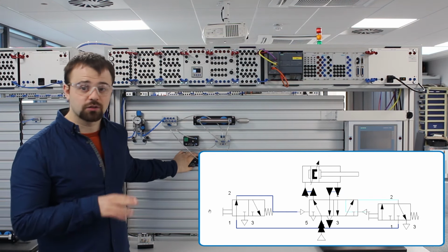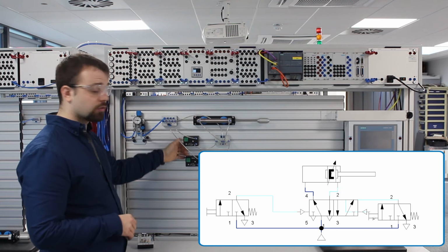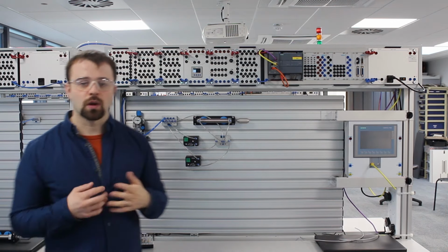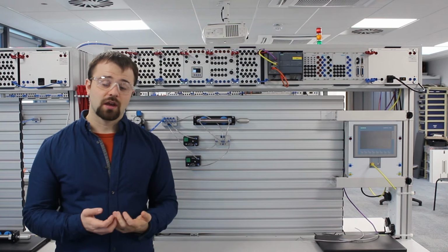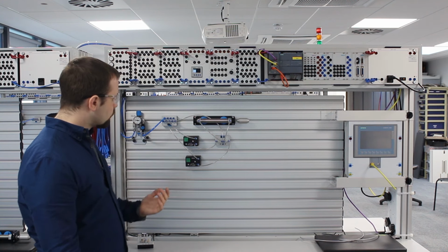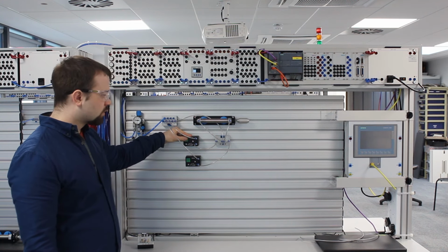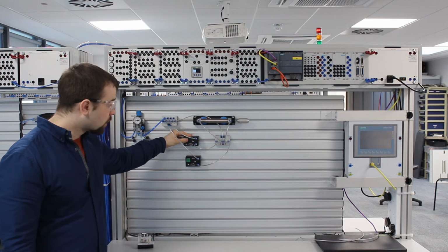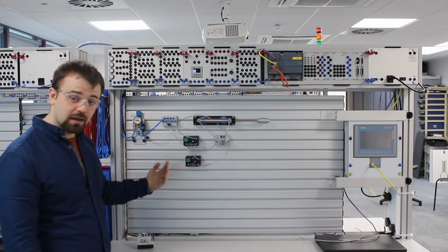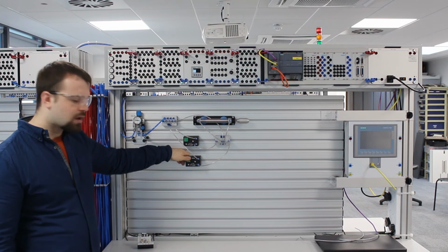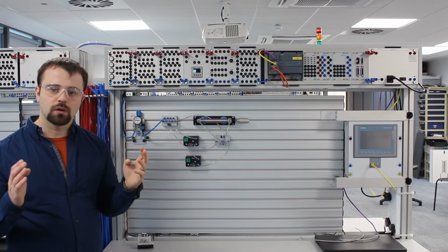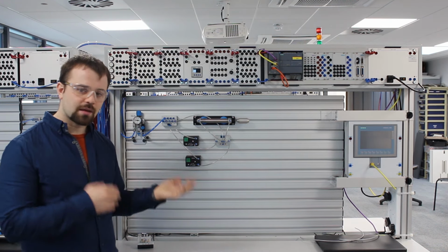You can't do that without a directional control. One forward, one back. So what if we wanted to take this one step further? Well, we could try and get to a stage where we have an oscillating cylinder. How would that work? Well, at the moment, the cylinder is back, so you would push the button to make it go forward. When it goes forward, it would hit a button which would make it come back, like this. So what we need to do is swap out these 2 buttons for roller switches. Let's have a look at how we would do that.